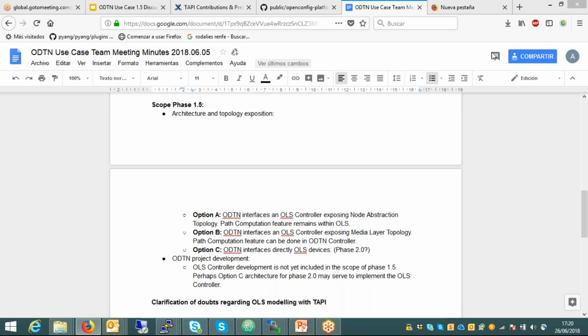Just with that, it is a considerable amount of development effort on ONOS, plus configuring the transponder part that we didn't take into account. It will also be necessary to configure the lambda. We need to account for the power configuration, and if we go for a realistic use case, we will also need the configuration of some sort of logical assignment between the client ports and the optical line ports. All of these are tasks that need to be done by the controller, and this is just assuming a logical topology exposure and the simplistic use case that Gary has mentioned right now.